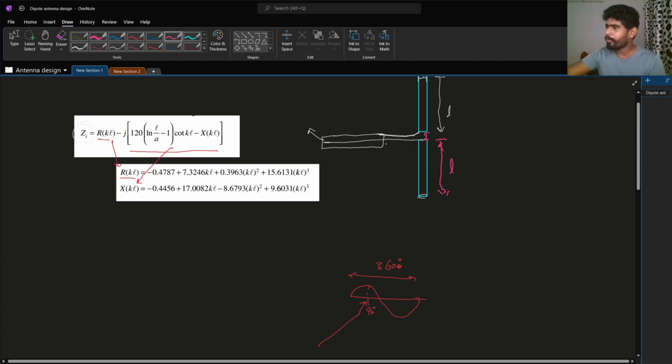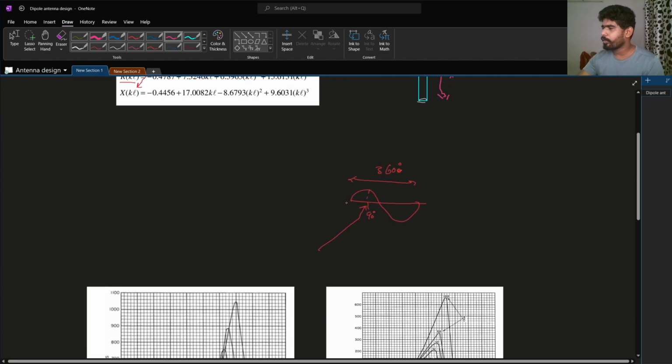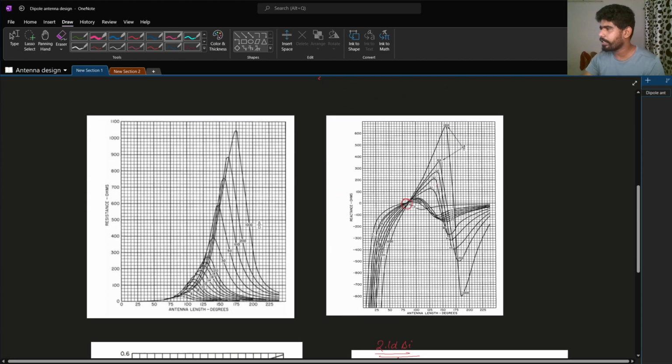This length should not increase; it should be placed as small as possible. By adjusting the inductance and the capacitance, you can match your antenna. Even if the height is increased, so the total length is increased, you can do some feed adjustment and match these sections to zero reactance. Okay, so that's all.